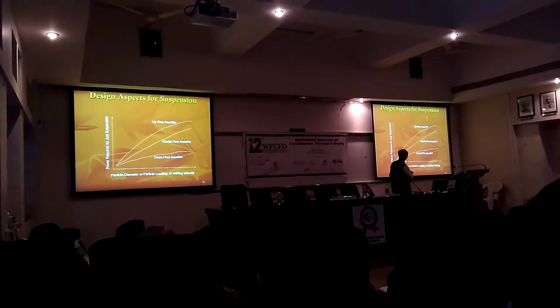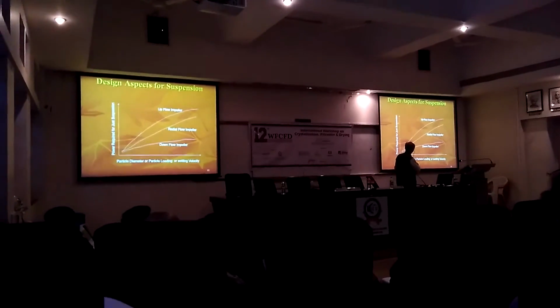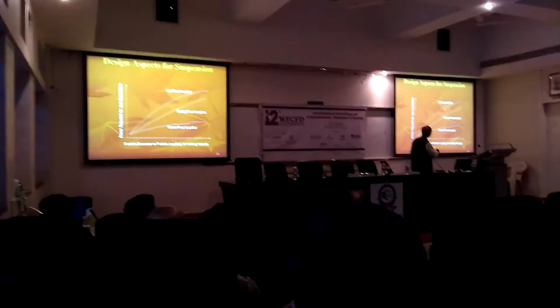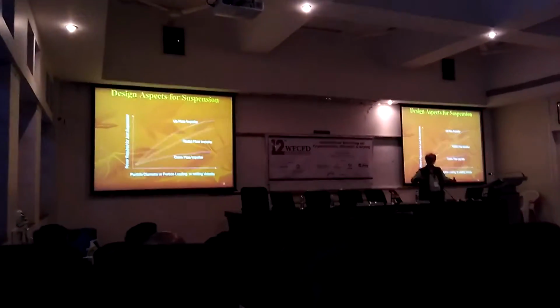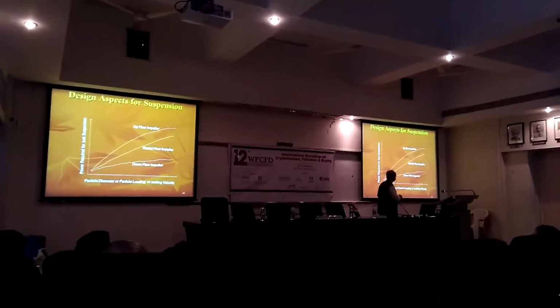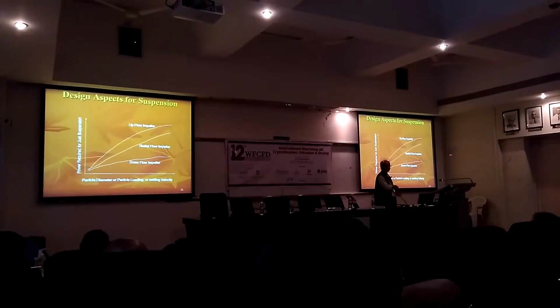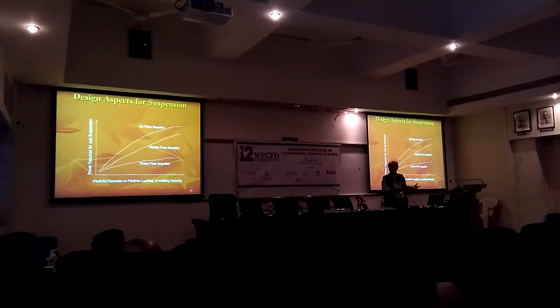And if you look at it, depending upon the type of impeller, this is the power which is required. If I use an upflow impeller, intuitively if I am interested in suspending the solid particles, I will use an upflow impeller. As compared to that, you will find the downflow impeller uses significantly less power.